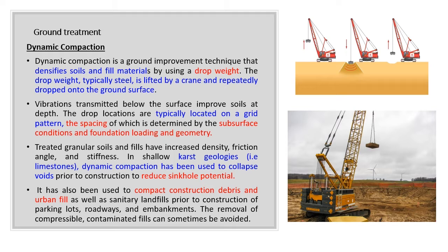layers, compacted, and consolidated. Where fill is built up in layers, the fill may take the form of unmodified materials as previously excavated, or soil which is modified or stabilized using additives such as quicklime and pulverized fuel ash (PFA) or cement. To achieve the desired effect, several passes may be required.